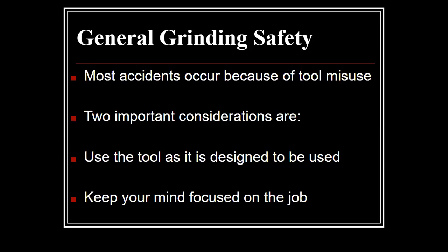like pedestal grinders, hand grinders, angle grinders, stuff like that, there are different discs we can use for different jobs. Now, just like a crescent wrench is not the best tool for working on a car, maybe a zip disc is not the best tool for grinding. So grinders have different discs, and we need to match up that disc to the job we're doing. Otherwise, there could be some unwanted side effects that could potentially put us in harm's way.